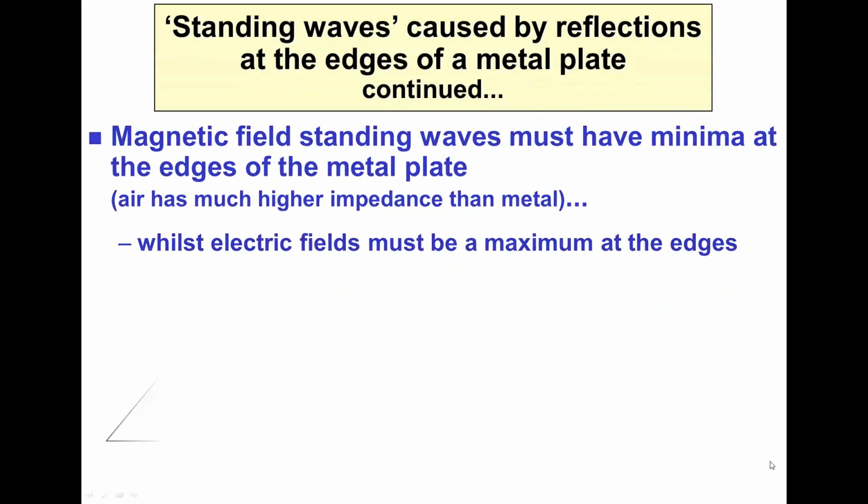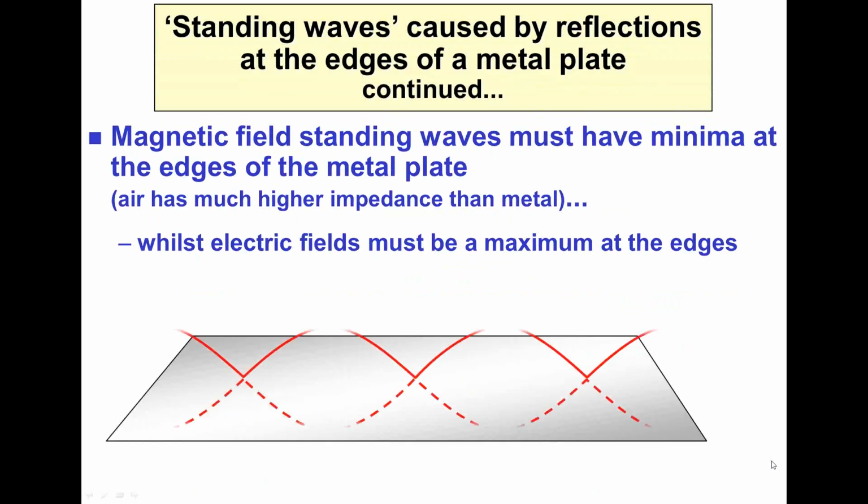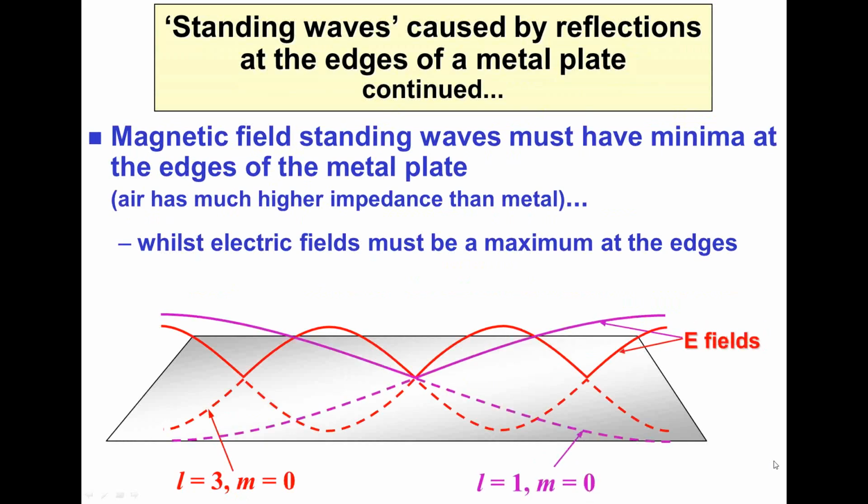And let's draw the same thing for electric fields, which are a maximum at the edges. And if you have an electric field close field probe, this is the sort of thing you'll see at the edges of your PCB ground plane.